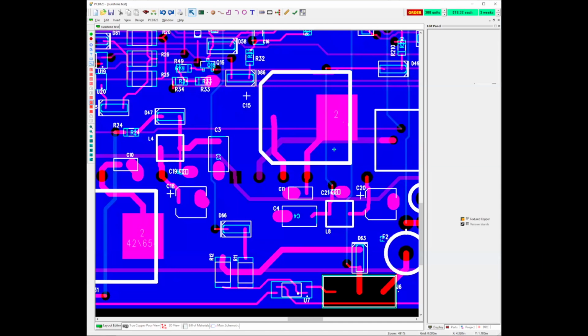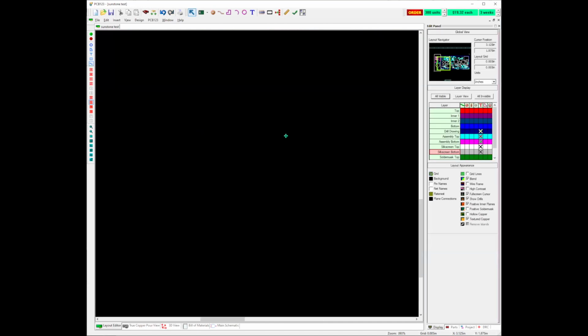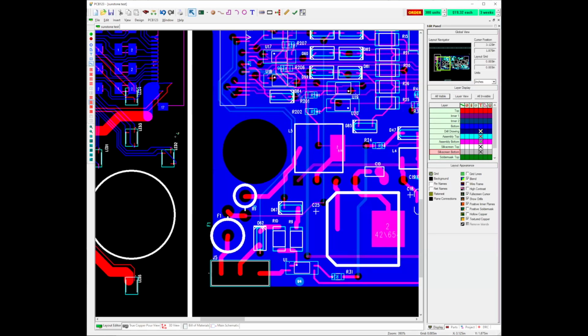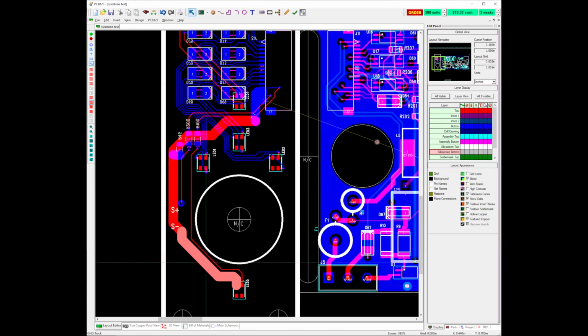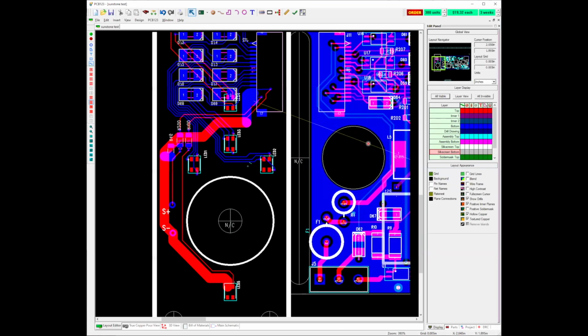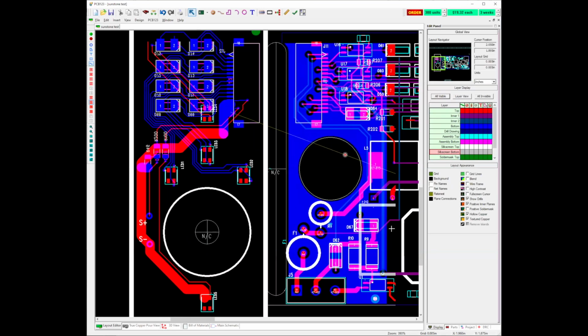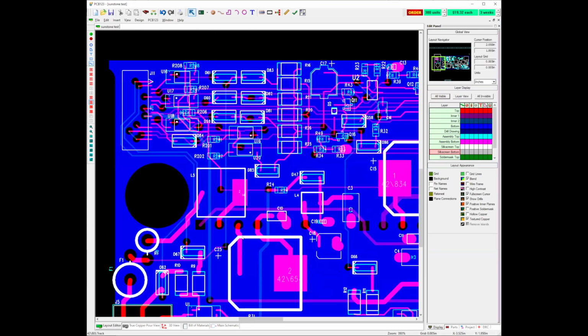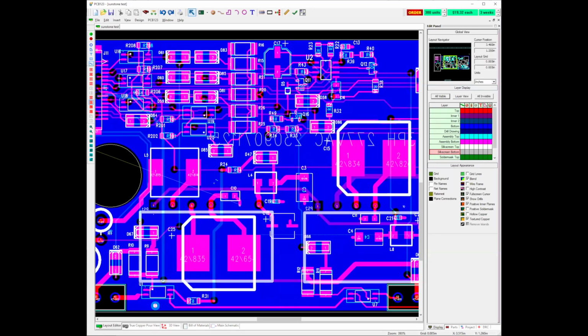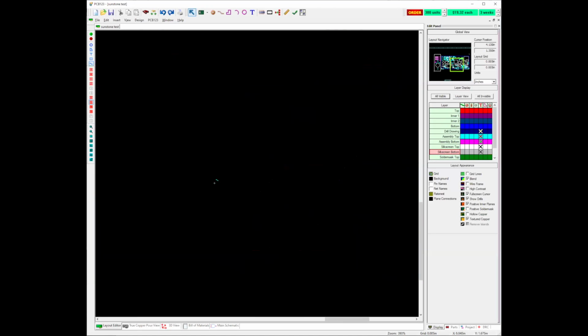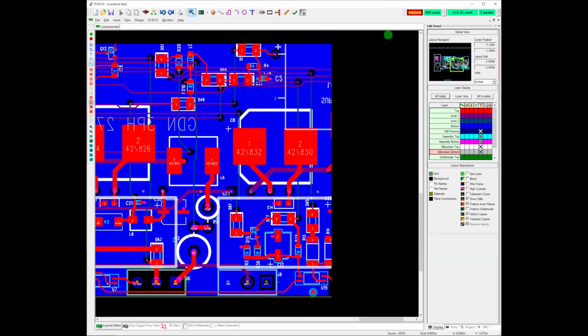But what I didn't take into account when I did that is that over here I've got this ground wire on my LED circuit that I changed to 0.1. Well, now it didn't seem to break anything because it's a pretty open area, but you can see how that can cause you some real grief downstream, that that makes a mess. And worse is if I've got a net that carries a lot of current, and I accidentally do that, change net width, and it's got other instances of that net somewhere else on the board.